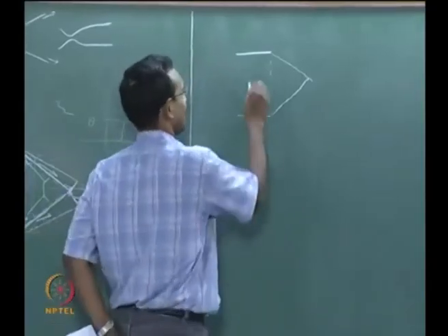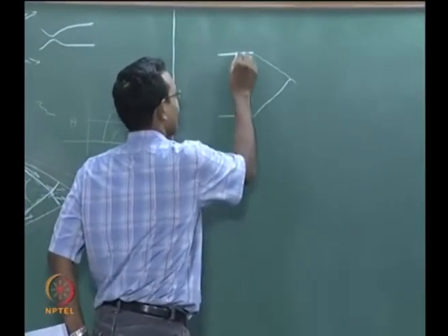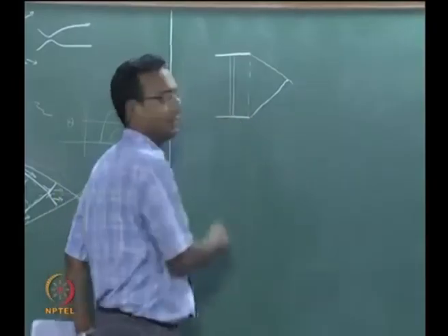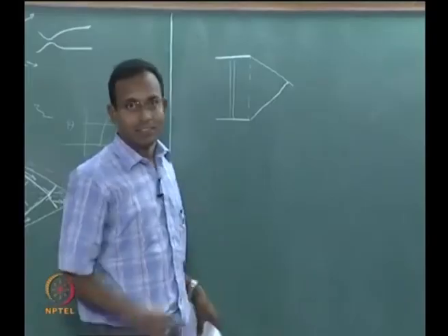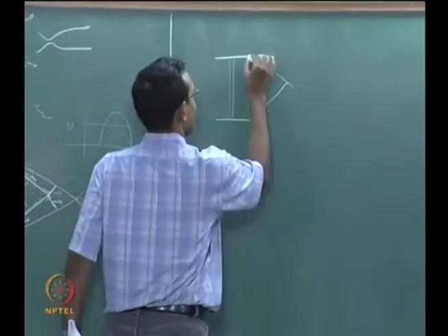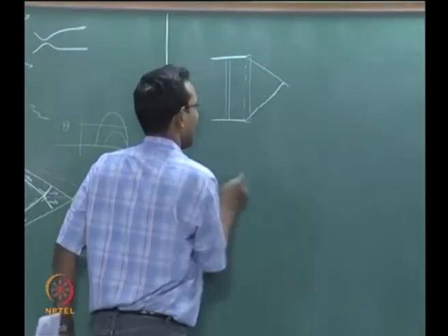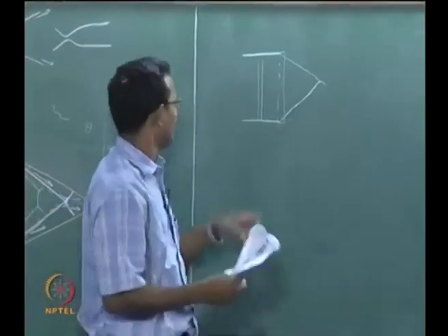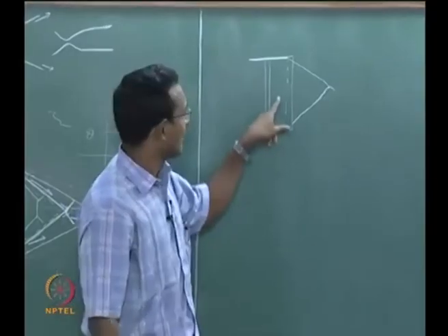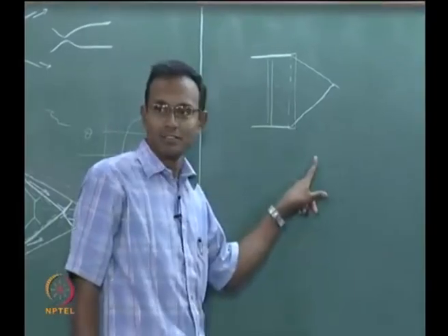Currently what is going to happen is, there is a slab of fluid, it is coming with some reasonable velocity, and suddenly when the slab comes to the exit, this corner is seeing higher pressure. Why higher pressure? It is an over expanded jet, this is over expanded compared to the outside world, okay.